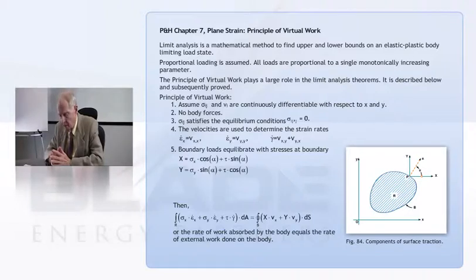We're going to only look at the principle of virtual work in cases where the stresses satisfy the equilibrium conditions. And the velocity field is such that you can derive the strain rates from it, and we assume then that definition holds. And then the boundary load, boundary traction equaling the inside stresses holds.